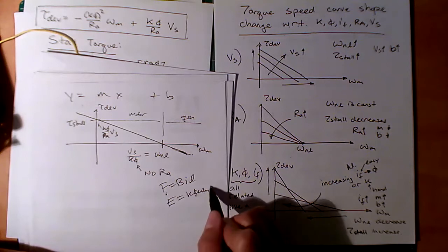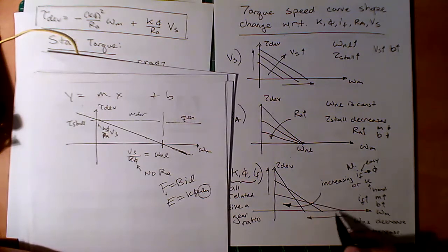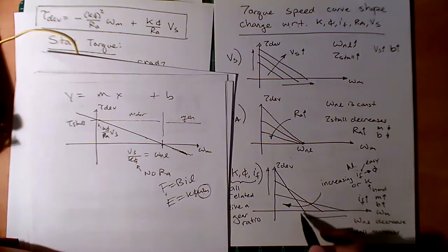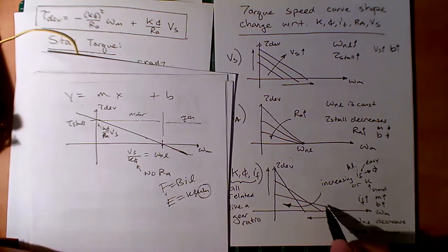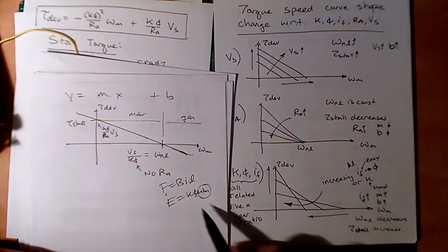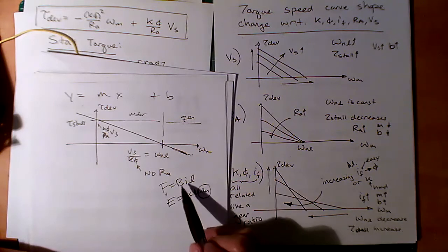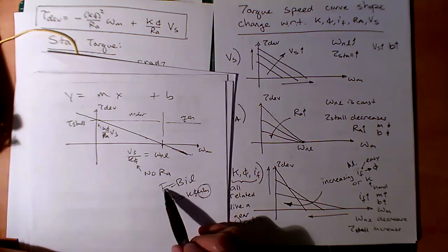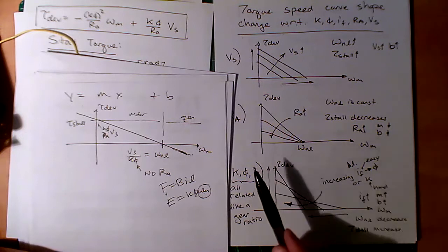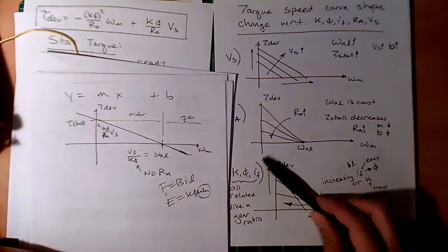But that only happens when you have some non-zero speed. Over here is where you have that non-zero speed, not here. When you have that non-zero speed, you are getting more back EMF, less current, less torque, and that's why it's rotating this way. Over here, without the back EMF term, so no back EMF to fight your current, you get a bigger amplification of current to torque, and that's why it rotates. So you could think of adjusting the phi as a kind of a gear ratio.